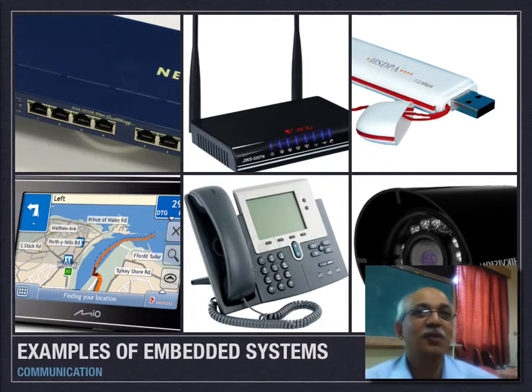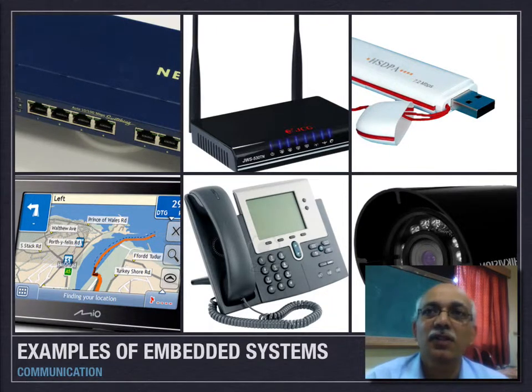So, the address bus would be quite big, correct? Now, do we have those many lines on USB? No, we do not have those many lines, correct. Serially 4 lines are there, out of which 2 lines are for VCC and ground and 2 more lines for signal, correct. So, all this data has to be serialized. That is why we call it a universal serial bus, correct.